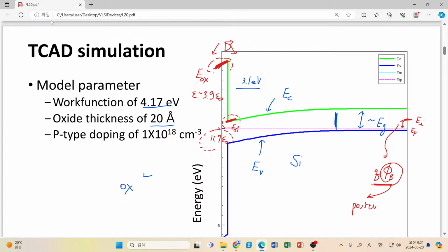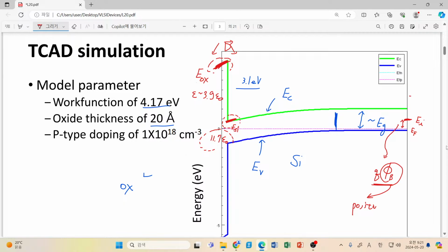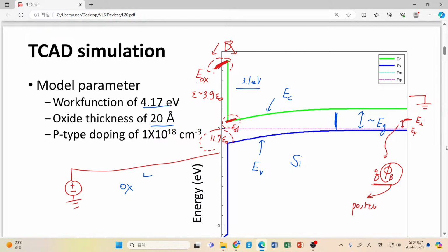So in this case, okay, this is the case we will consider from now on, and please have a look at 4 different graphs out of this same system. The only difference is, yes, I just connect the ground 0 voltage to this substrate, so this voltage is just fixed, and instead I change the voltage applied to this gate part. So gate voltage is always changing.